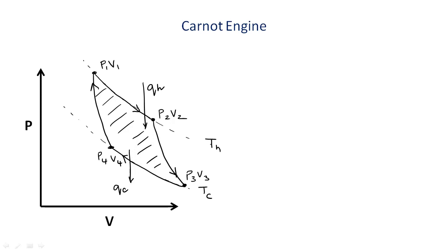There are a couple of points to note here. The first point is that it is essential that an engine has a cyclic process at its core so that it can continue generating work by repeatedly going through the cycle. A simple expansion of a gas against external pressure, although does work, is not an engine because the gas in that case has not returned to its initial state and cannot be used continuously for doing work.